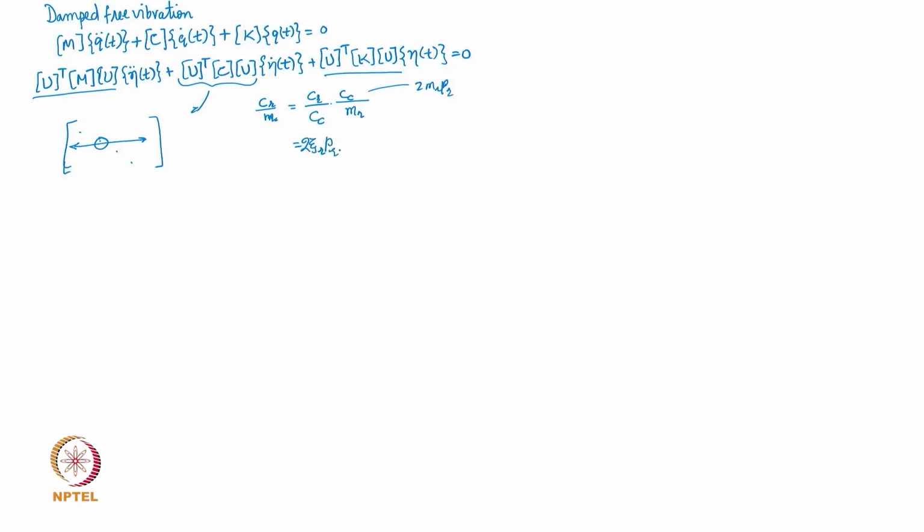Okay. So then we say that the damping matrix can be replaced by modal damping ratios, and each of these modal damping ratios will have to be identified. So each of these diagonal terms will now be quantified through modal damping ratios, and these should be called the equivalent viscous damping factors.